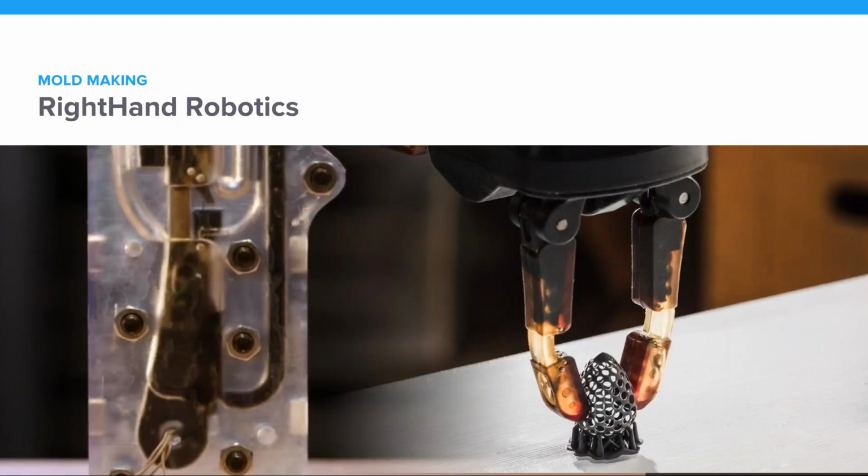Next up is Right Hand Robotics. This is a great example of using 3D printed molds in production. What they do is make robotic fingers and grippers for the scientific community. So they 3D printed molds. They 3D printed these plastic parts that go inside the molds. They put them all together, and then they inject room temperature vulcanizing rubber into the mold, and it casts it, and then they pull the part out. And they actually send that to the customer. So this is a great example of using molds in the real world, and I'm going to talk about them a little bit later when I get into digital direct manufacturing at the end of the talk.